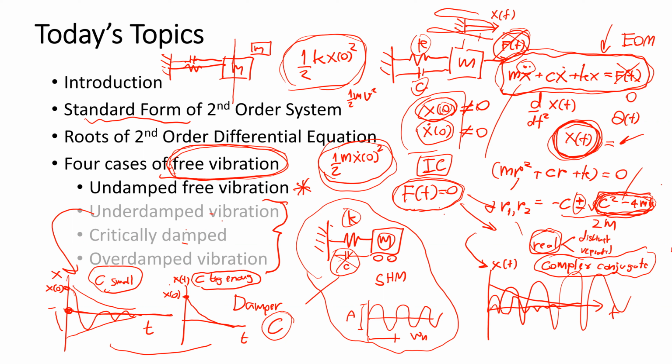If the damping is more, when the mass is on the right hand side of the equilibrium point, the vibration will begin. The mass will go back and pass through the equilibrium point and reverse, and finally stop by the effect of the damper. But if the damper is big enough, the mass just slowly moves and stops at the free length of the spring.